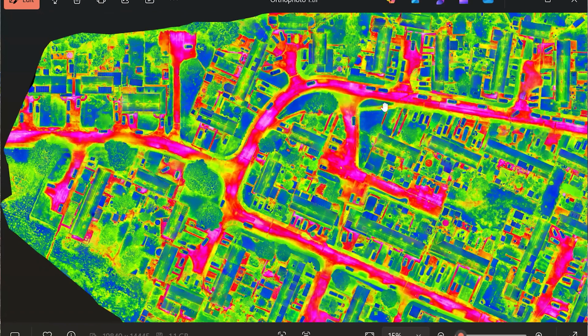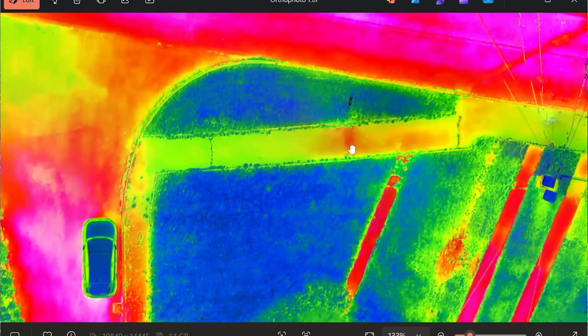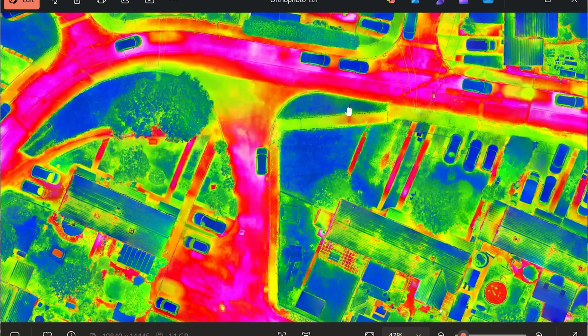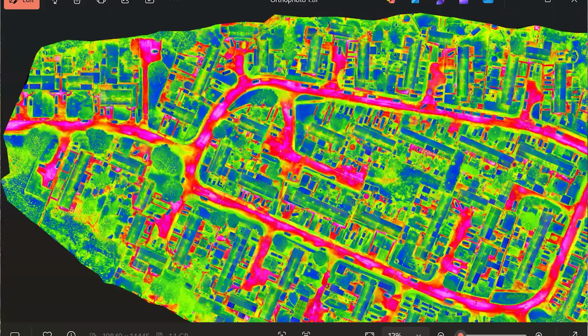For instance, we identified there's a street light here which is underground. This was a 37-degree day, so we did it at night. But obviously we've got a heat source coming from the ground, so a potential electrical problem underground there for this lamppost. So a lot of other stuff got thrown up, but it's good because then we can pass this information on to the different contractors, so they can look at where they're working and fix the problems that we would have never found without it.